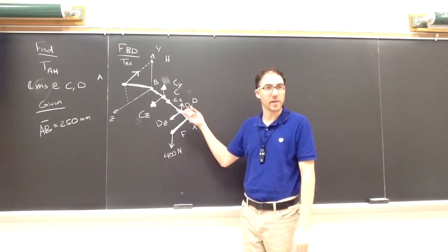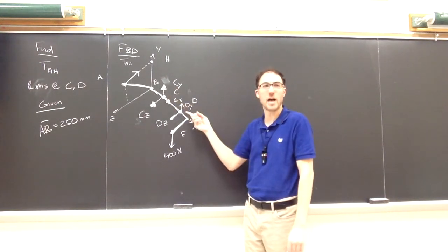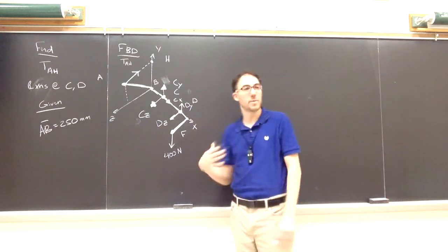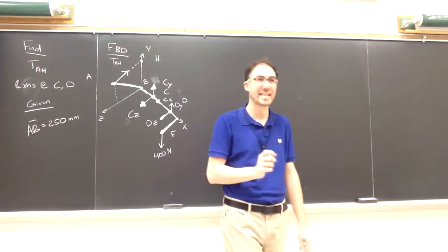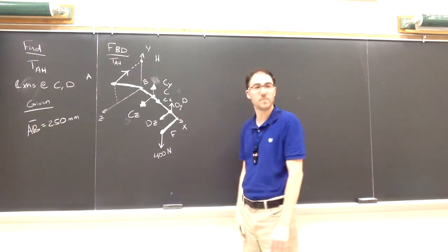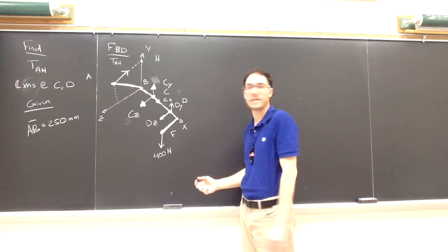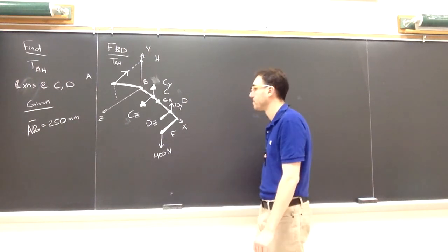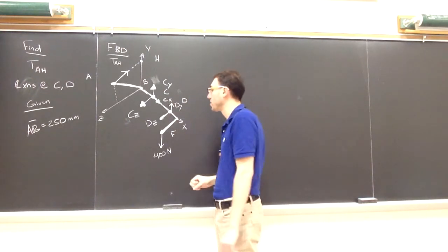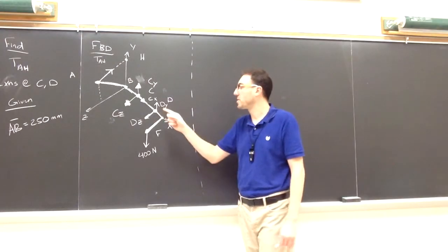This is a journal bearing, and the journal bearing allows the shaft to move along its longitude, or the shaft to move through the bearing. So because it does allow that motion at D, there will not be a force at D in the X direction. And as we just discussed, because they're properly aligned, there'll be no couples at D either. So D will have those two forces, one in the Z and one in the Y. Right, so our supports are all there.